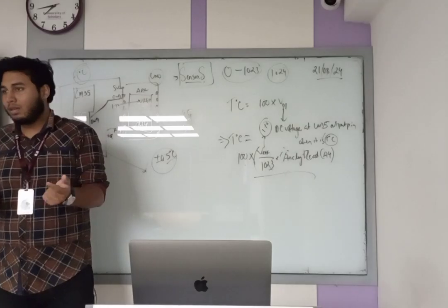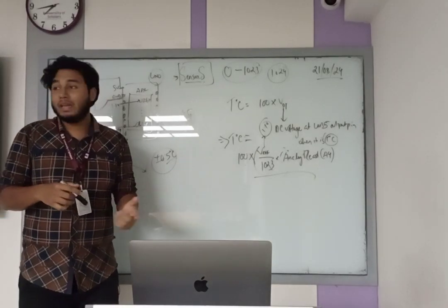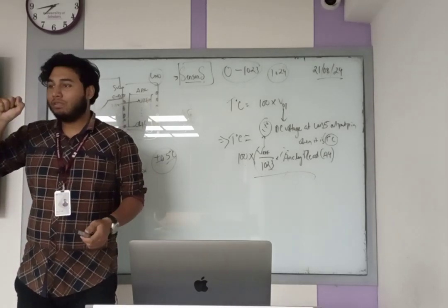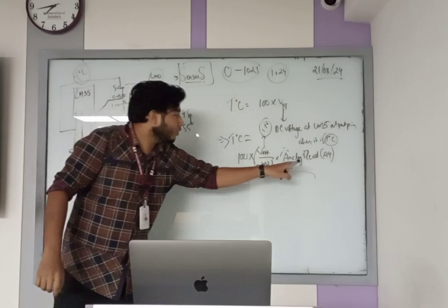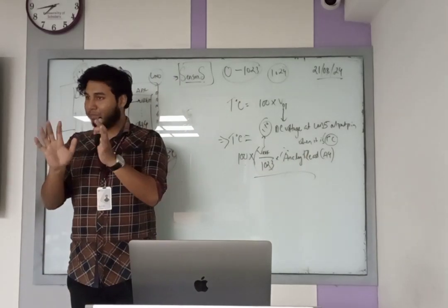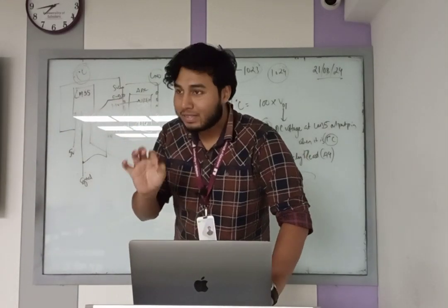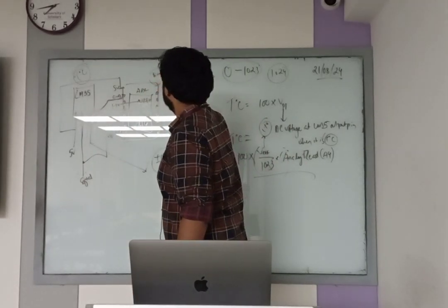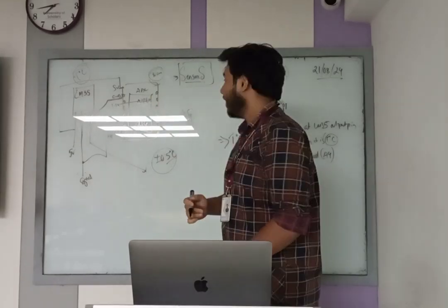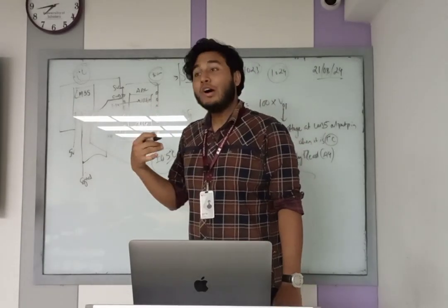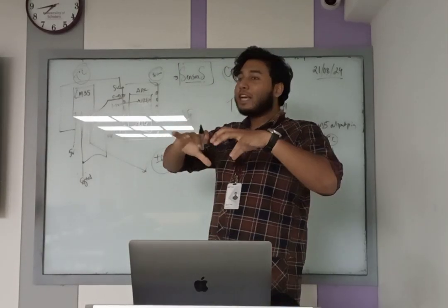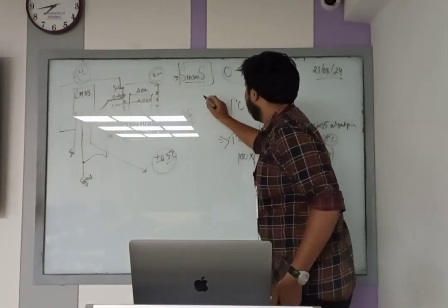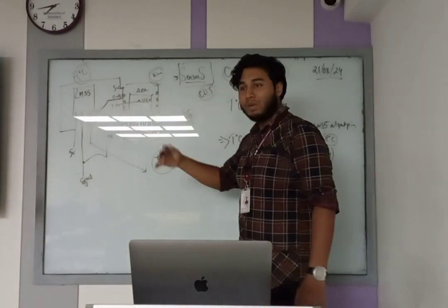Specify a pin. I'm going to work with a specific pin like A5, and the sensor's value is going to be read through this A5 pin. Do you get my point? I am going to build a setup with the Arduino Nano connected with the LM35 sensor, where I have to take the reading from the environment with the pin number, channel 5. Now build this connection.